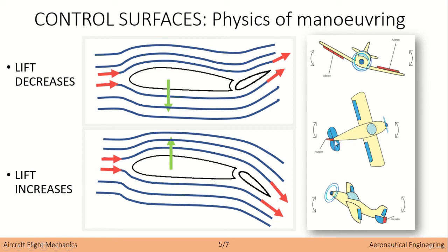It is applied in many different areas. As you can see, the ailerons are able to produce a net difference in lift. Also, the rudder will produce a difference in lift on the specific side of the rudder, okay? And this will actually rotate the aircraft. And in the same way, the elevator will actually provide very similar forces, okay, but applied to the tail.